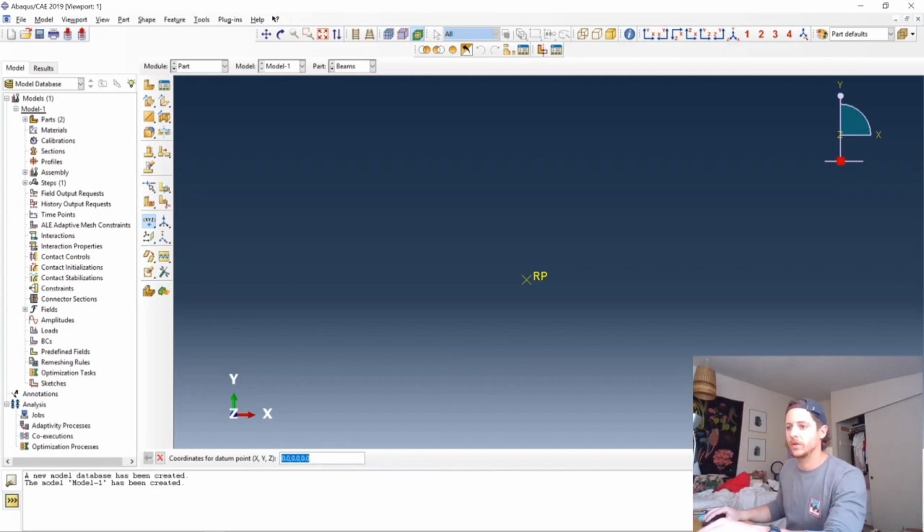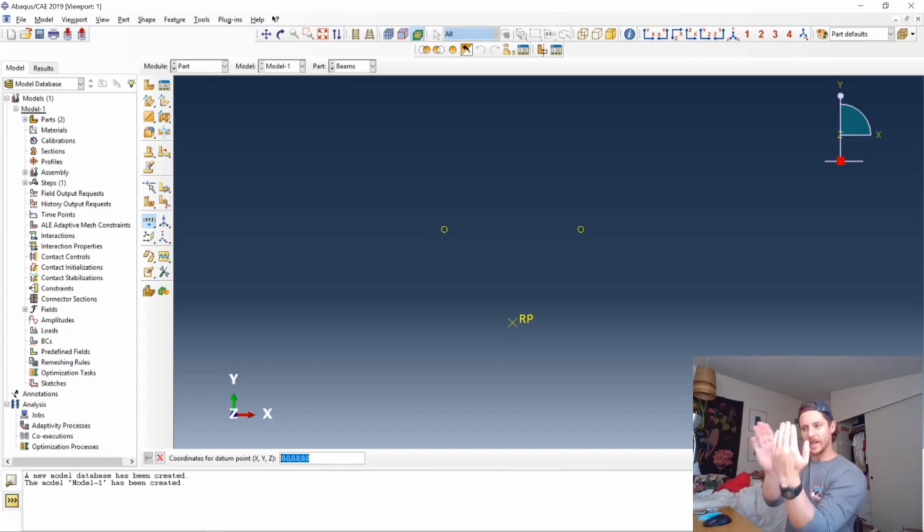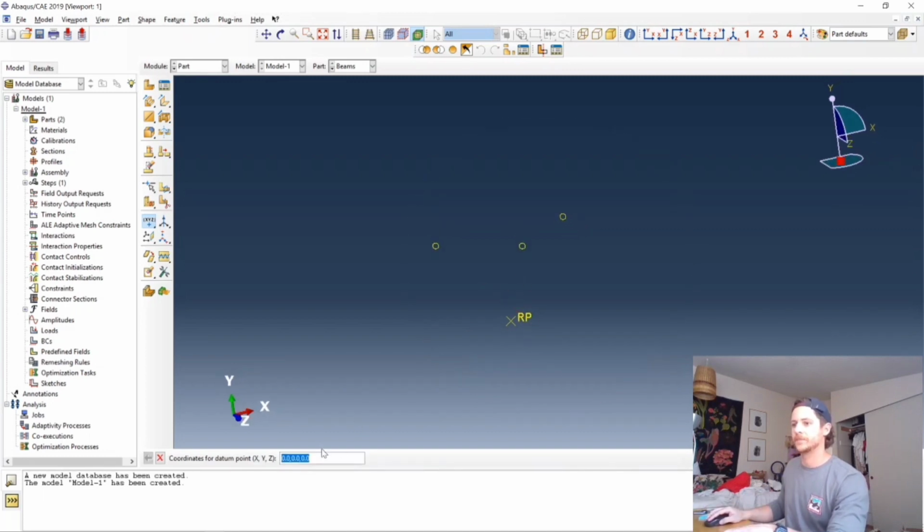Okay, so we're going to go 0.12 in the x, and then 0.16 in the y, so that would be there. Let's do the exact same thing, but negative here, so negative 0.12, 0.16. Then we got to do it out of plane too. So here, that's going to be in the z component. So that's going to be 0.16 and then 0.12, and then same 0.16, but negative 0.12 here. Okay, good. So we got these here now. Now we need to make a wire element.